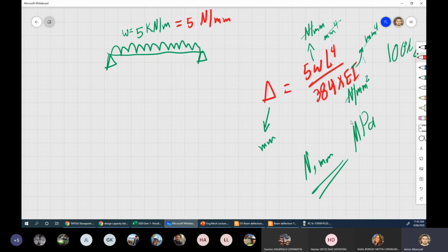Okay, always use it in MPa. Again, you see, without me even thinking why we're using this and that, without me overthinking things like what we did today, I used the right numbers here and I could have got the right answer if I put the numbers in place without even thinking of the units. Why? Because I know the units should be uniform, that's all. So you can't use GPa. It's not good to use GPa. It should in theory give you a wrong answer if you use GPa with millimeters and your forces in newtons or Newton per millimeter. All good? Yes, I just didn't get the same answers, but we can see when we go through the exercise. Yep. All right, we'll do that today.